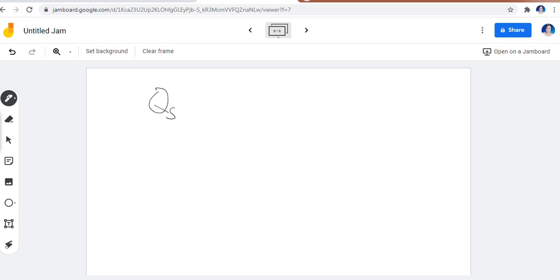Your sensible heat can be computed using the basic thermodynamic principle of m Cp delta T. In this case, we will use the mass of dry air times its humid heat, or the average specific heat, times its temperature, T1 minus T final, and then 1 minus the bypass factor.